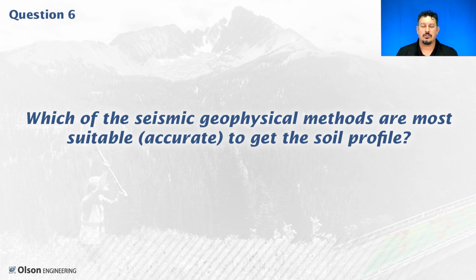We would almost always want to just use a surface method, if we can use a surface method, because it's usually faster, and faster in the sense that you don't have to put in a borehole or multiple boreholes if they don't already exist. If boreholes already exist, go do the borehole method. That'll be the fastest in the field, a few hours probably, and the interpretation is relatively easy.